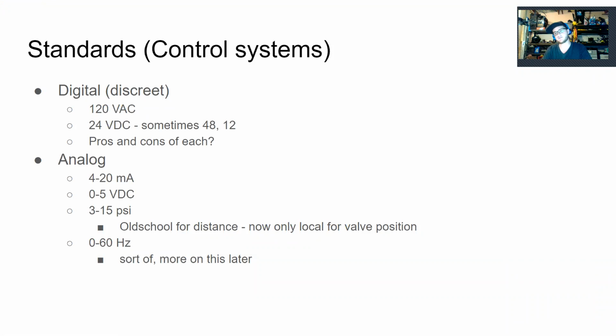You might be asking, well, why don't you just use an electric actuator on that valve? You can buy valves that have that, but those electric motors to control valve position are way more expensive. So it's way more cost effective, if you have industrial compressed air supply available in your plant, to use air to control your valve stem position. You have to size your valve correctly, and it'll have dampening and return springs in the valve, so that you can just control from 3 to 15 psi on your valve and get your desired position.